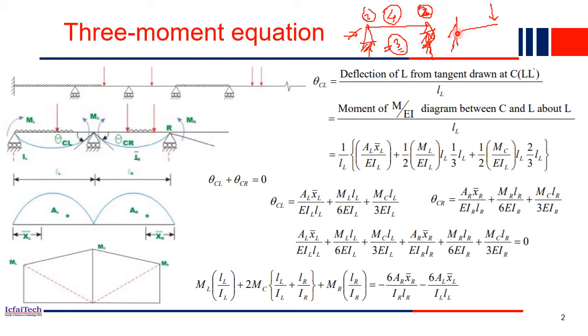Similarly, if you have fixed ends, for example this beam with the left hand side fixed and the right hand side also fixed, in that case you have three unknowns here and three unknowns here. So in total you have six unknowns, right? And you have three equilibrium equations. So this beam is indeterminate with the order of 3, because 3 unknowns we can compute using the equilibrium equations, whereas the other 3 we can't.